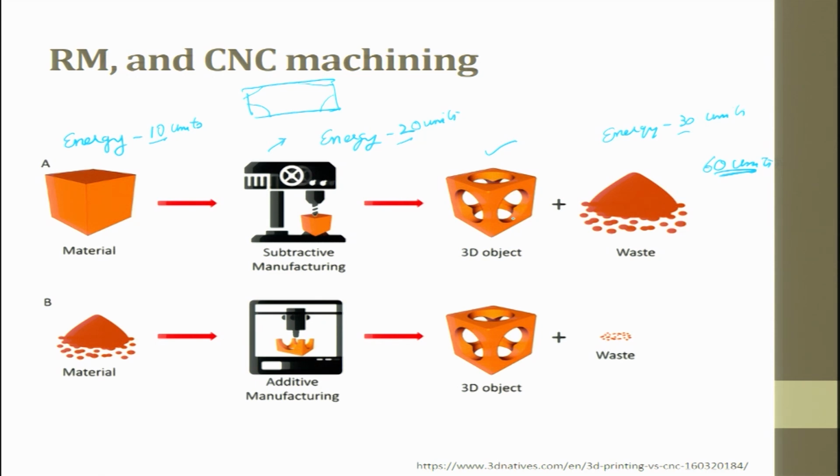So, making this, every time in a conventional normal milling machine, we index and try to make it. In a CNC machine, again a normal CNC machine cannot do this, you should have a 4-axis or 5-axis machine which indexes in the fixture and you start machining it.